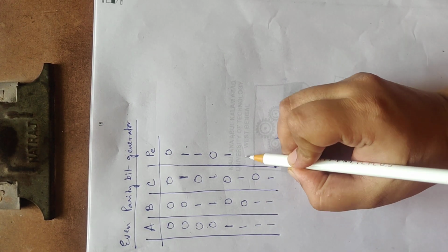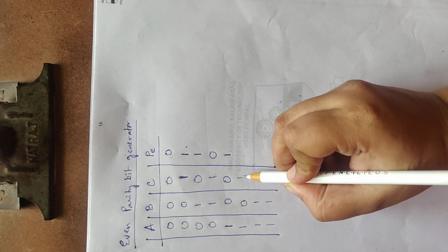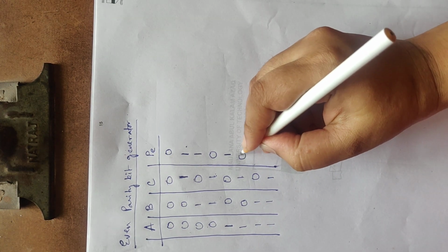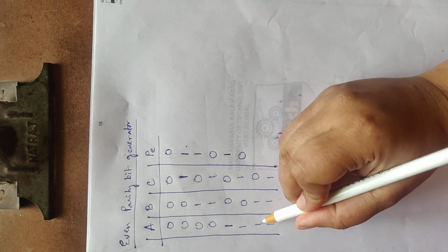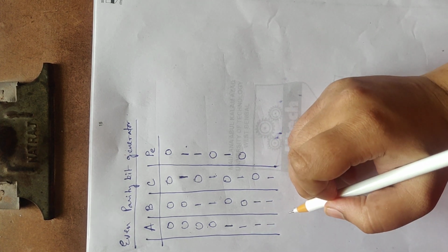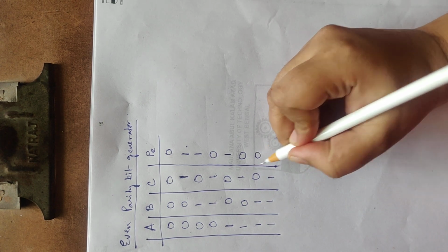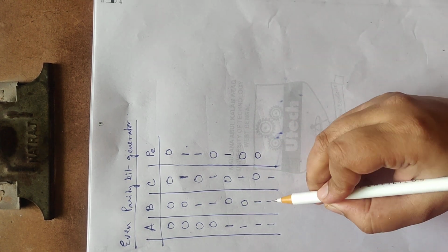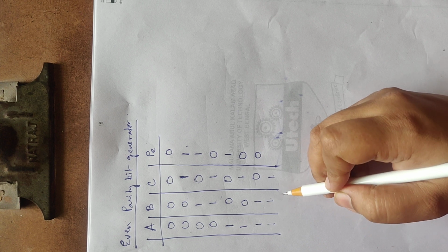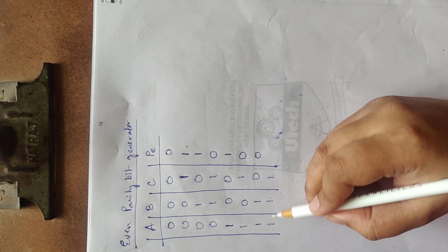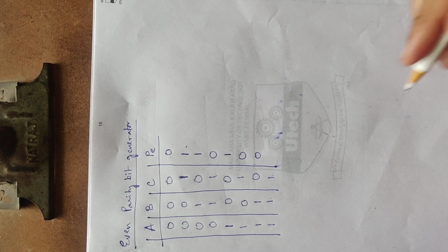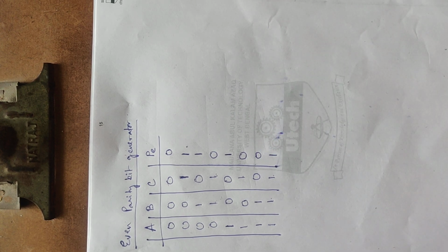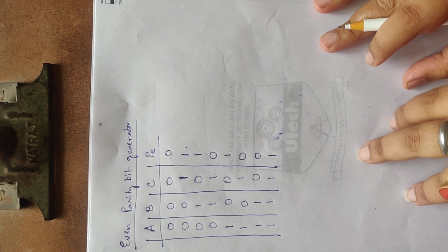Then for the next line, we see number 5. We have already 2 ones here. So the parity bit will give me 0. Next for this line, we see for 6, both of them are 1 here, which is making an even number of 1s. So here will be 0. And finally we see these 3 are 1, that is for decimal 7. So what do we see here? Since all 3 are 1, that means an odd number of 1s is present. So to make it even, I would have to put 1 at the parity generator bit.